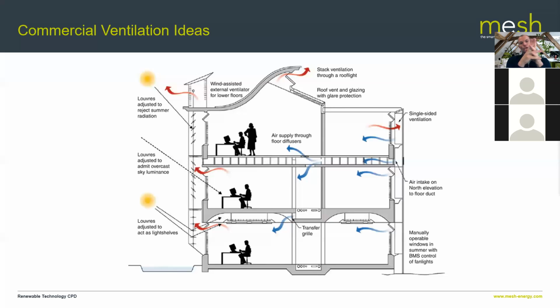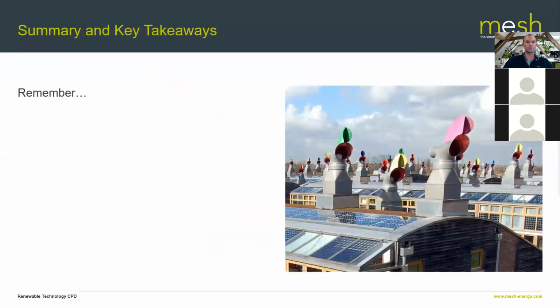And, although we've talked about overheating, you've got to make sure that the building performs in winter as well as summer. So summer overheating, great, you can use these effects, but you do have to think about ventilation as well during the winter when you're trying to keep warmth in, but you're trying to make sure that you're ventilating the spaces enough. So you might need a slightly different strategy, or maybe a hybrid strategy, or slightly mechanically assisted strategy for some buildings that you're working on as they get more complicated and there's more needs from the occupants through the seasons. So again, a really quick whistle-stop tour through commercial and domestic and some of the main effects.